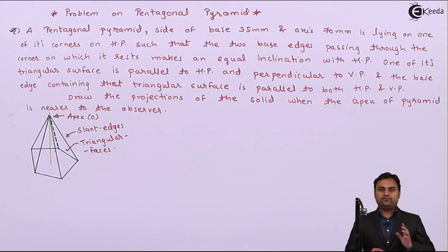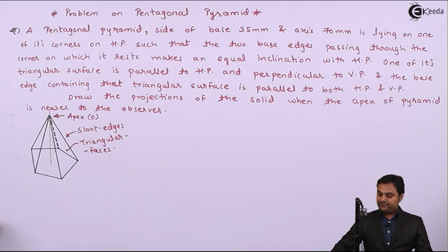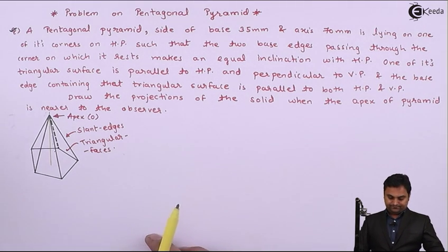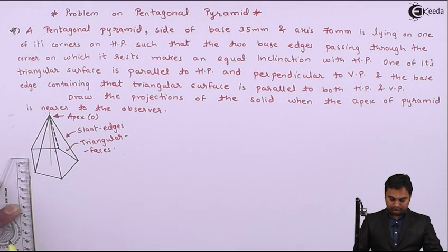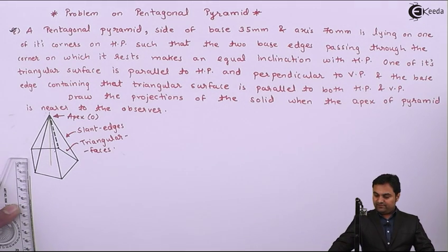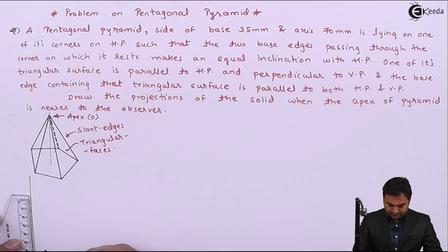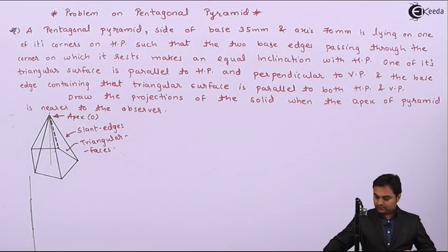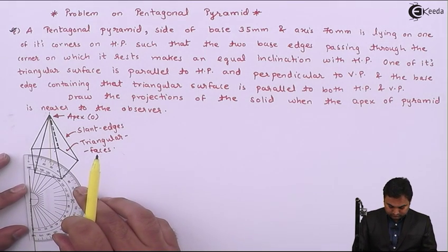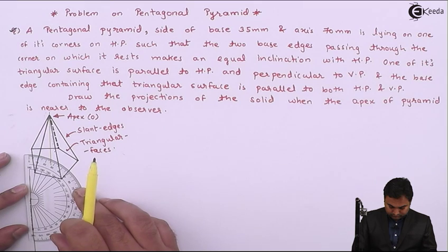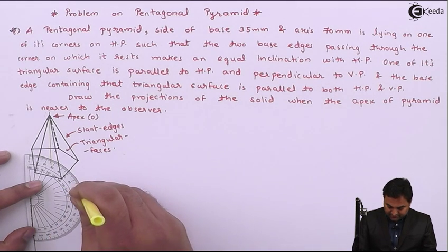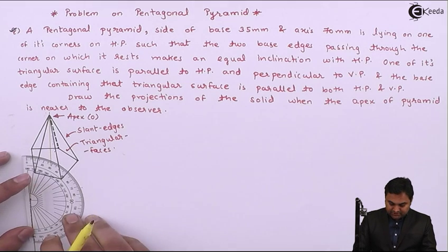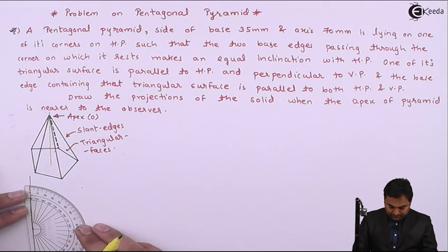So when the condition is of corner, we will draw it in this manner, which I will explain here. Base edge is 35 mm. Marking 35 mm. Measuring 72 degree, because the edges of the pentagon are inclined at 72 degree. So measuring it from both the points.